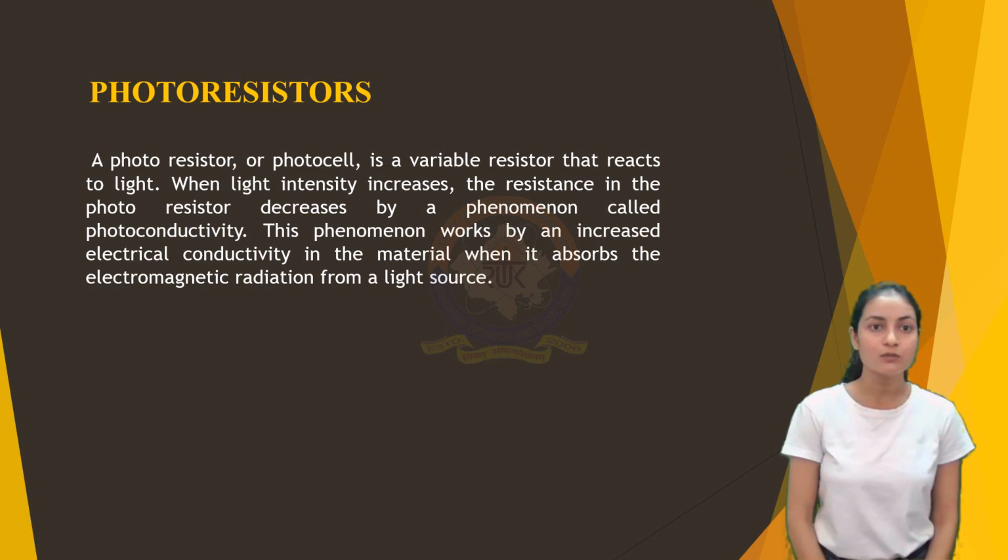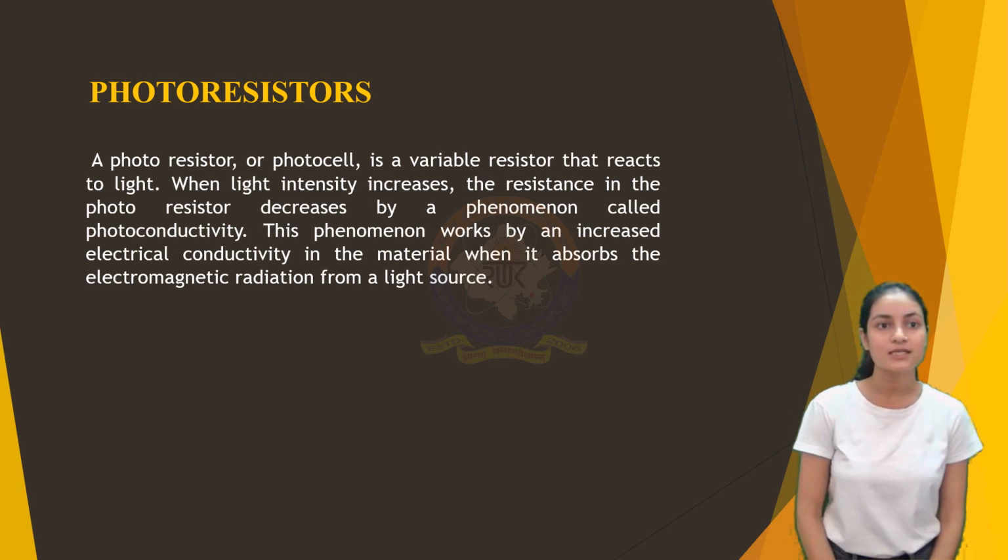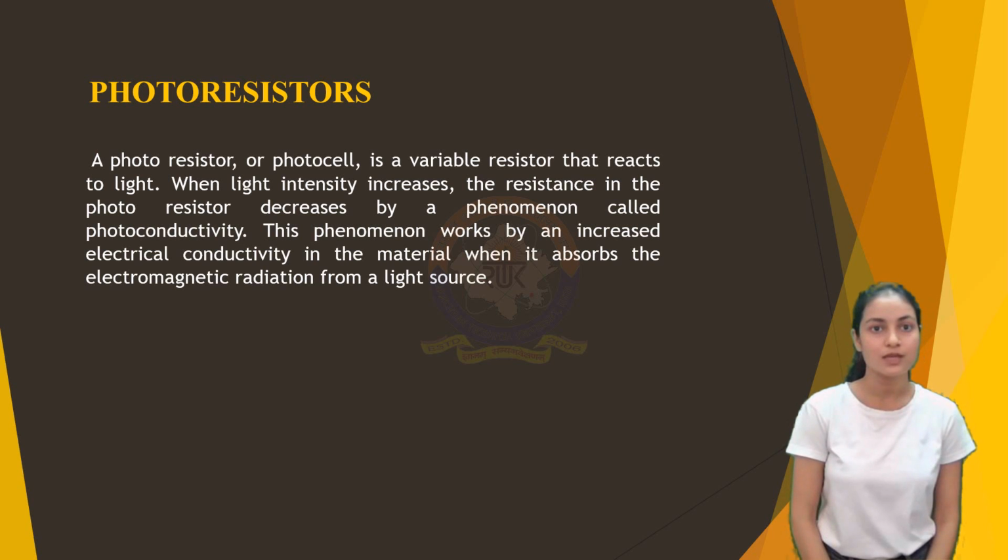The top and bottom units give the input to the pitch axis and left and right give input to the main axis. To align the self-aligning solar panel with the sun and optimize the output, the 2 rotational axes require a way to power the rotating movements and trace where and when the axis will rotate. Servo motors have the ability to achieve this but lack the accuracy needed. Stepper motors, however, have a greater accuracy and are therefore best suited for this type of project.